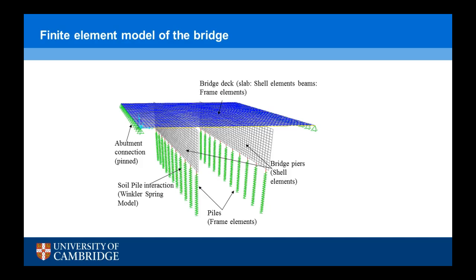Initially we created a finite element model to simulate this behavior, because before installing the instrumentation, we wanted to understand what sort of mode shapes and natural frequencies we are looking at. This is the finite element model that we developed. It was using CSI Bridge commercial finite element software.